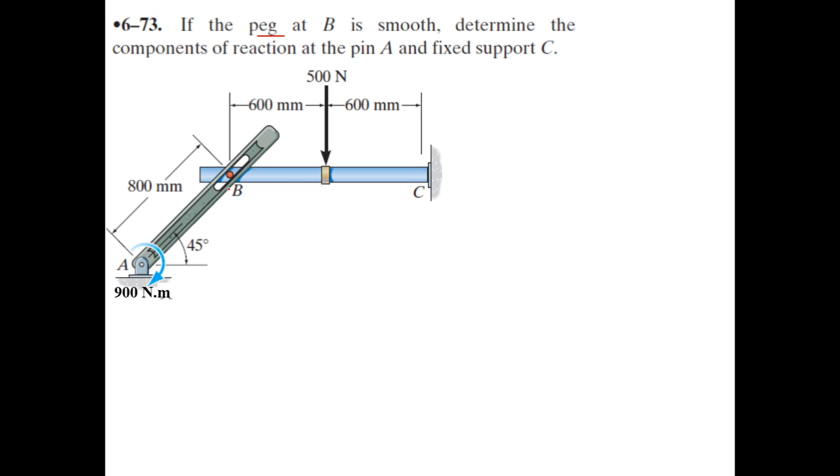So this means that both these members are fixed, and a frame is a mechanical structure that supports the external load, but its members are always fixed. So this means that this structure is not a machine structure, but it is a frame structure, and obviously it is not a truss structure. So we cannot use the method of sections to analyze it. We need to develop some strategy while solving frame structures as well.